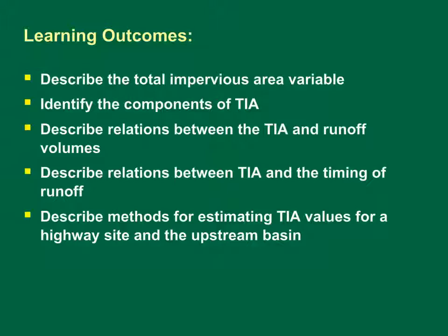The easiest way to get an estimate of imperviousness and other basin properties is to use the USGS StreamStats web application in states where it is available. If you have GIS skills, the National Land Cover Data Set from The National Map can be used to derive TIA estimates. If you do not have GIS skills, TIA can be estimated from land use areas, the percent developed area, road density, or population density. Appendix 6 in the SELDM Stormflow Report provides detailed information and regression equations for each of these methods.